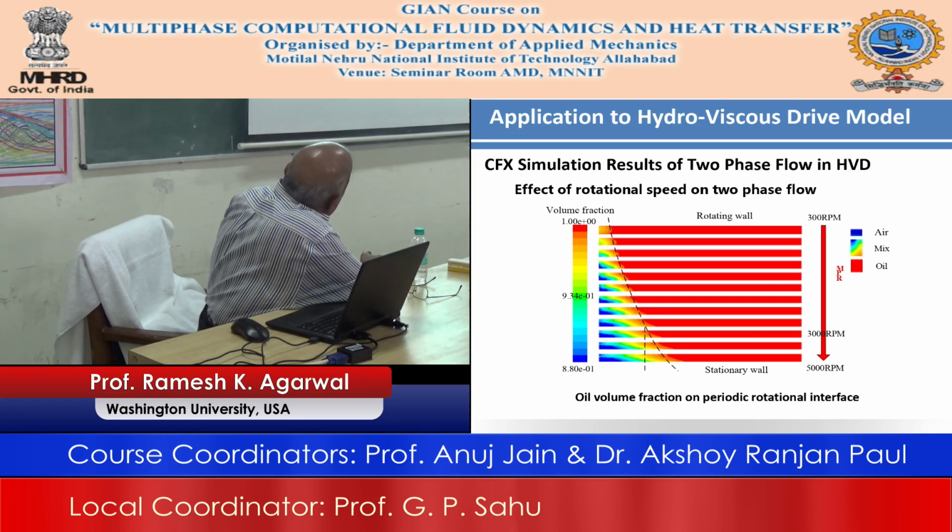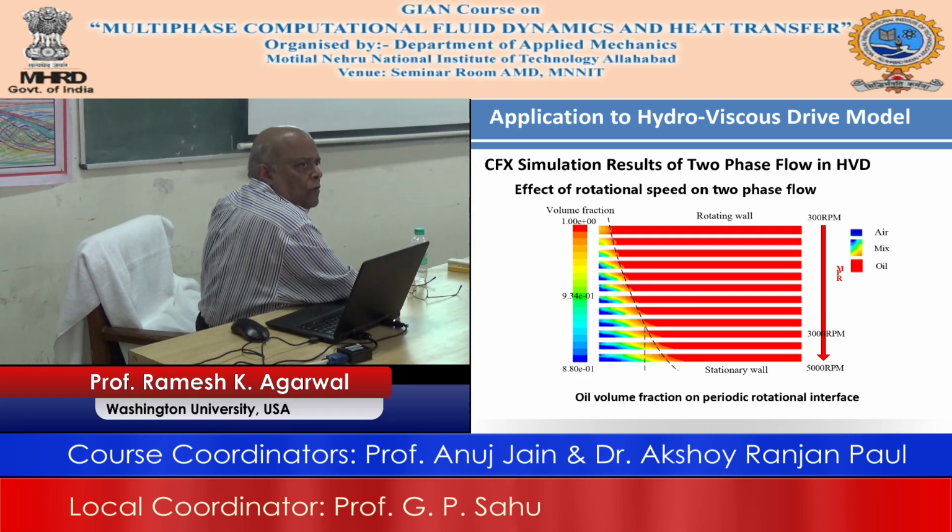So, this area you can consider as a cavitation area. This is pure air, this is a kind of mixture of air, and the reason you get this is that on the grid that we get, the value of alpha is such that this is the air, so alpha is equal to 0, alpha is equal to 1 here, and in between alpha has a value between 0 and 1. Okay. Are you with me on what I am trying to do? So, this is the result that you get, and this is the cavitation. The idea is that you want to prevent it.